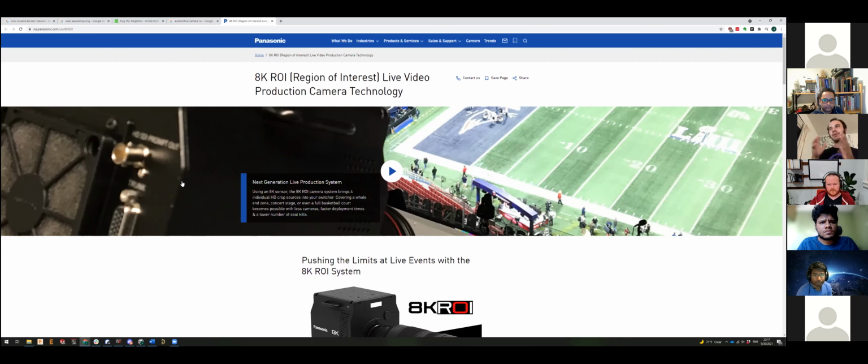So yeah, what I'm getting at is a lot of these sensors, if you bin it, it runs faster. And if you do an ROI where you look at the full resolution but a small section, it's a readout thing. It's a bandwidth thing to just read it out. Because a lot of these sensors build up the signal and then have to digitize it.